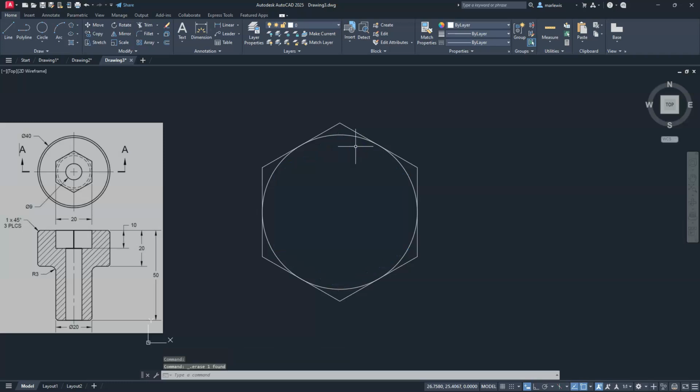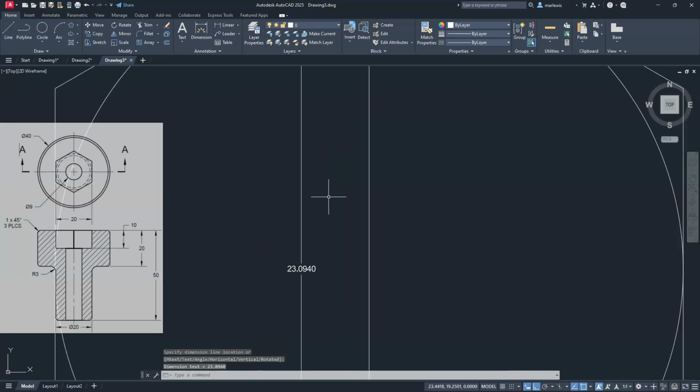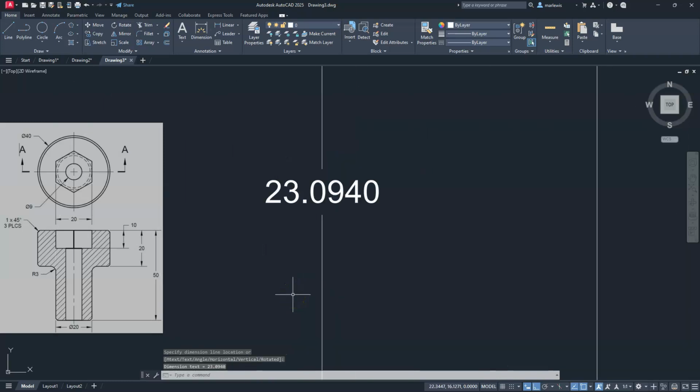All right, so we have this information going on, and I'm just going to draw a line from this endpoint here going all the way up to this endpoint. Let's turn my ortho on, and now I need to know the length of this line, so I'm just going to give it a distance. I'll type in DLI, hit enter. And I'm going to go from this endpoint to this endpoint. Now it's going to be a small number. And you can see that it's some kind of super weird number. I didn't expect this number to be some exact whole number.